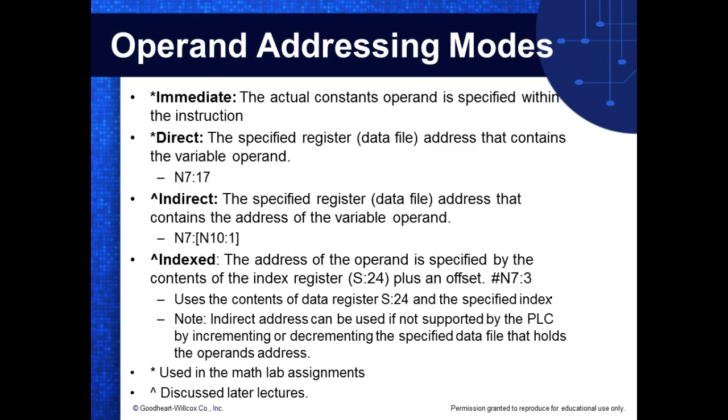We could bring it in from the accumulators of a counter, or we could bring it in from the preset of a counter, which basically could be a variable too. I think we showed y'all how we could use that as a variable too, right? So the preset on our counters, we were using constants, or we were using immediate addressing.